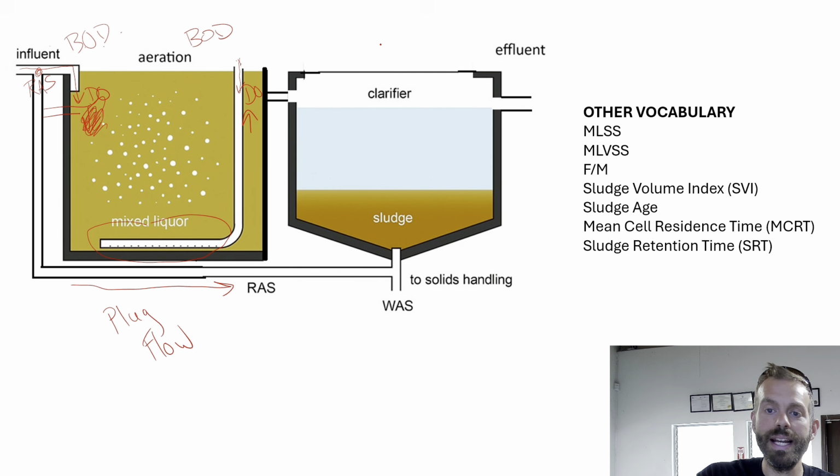Now, when it comes to the different stages, I like to say that in aeration, we resolve the BOD. In the clarifier, we resolve the TSS. So we just talked about how we resolve that BOD. The microorganisms consume the matter, and then they have a dissolved oxygen surplus towards the end. So then it transfers over, and this is a constantly flowing system in a circle, and you always have influent coming in. So this aeration basin's constantly flowing, okay? And it's moving to a different process. And so we'll be going over to now the clarifier.